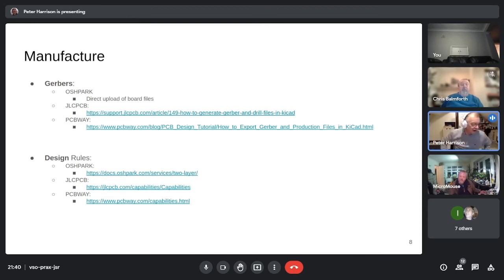If you order them from JLC PCB or PCB Way, they have instructions on how to generate the Gerbers to their specification, and they have specific design rules pages for your reference. Either of those will deliver. You can have 4 of these per panel, 5 panels delivered to you for about $25. So you can make 20 of these for about $1 each or £1 each or something.